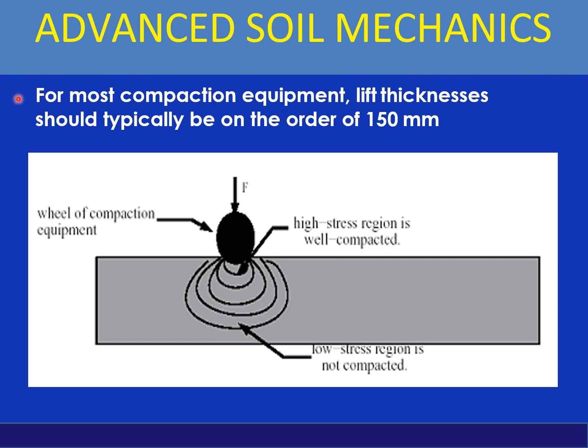For most compaction equipment, lift thicknesses should typically be on the order of 150 millimeters.